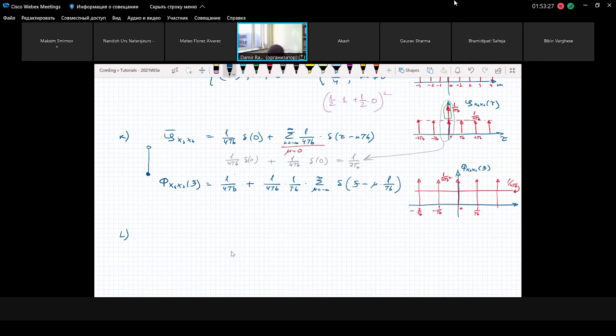We say that our transmit signal can be represented as a convolution between 2EB under the square root times the basis function with the sequence of bits that we transmit, x delta t. What we need to find is the power spectral density of this signal u(t).